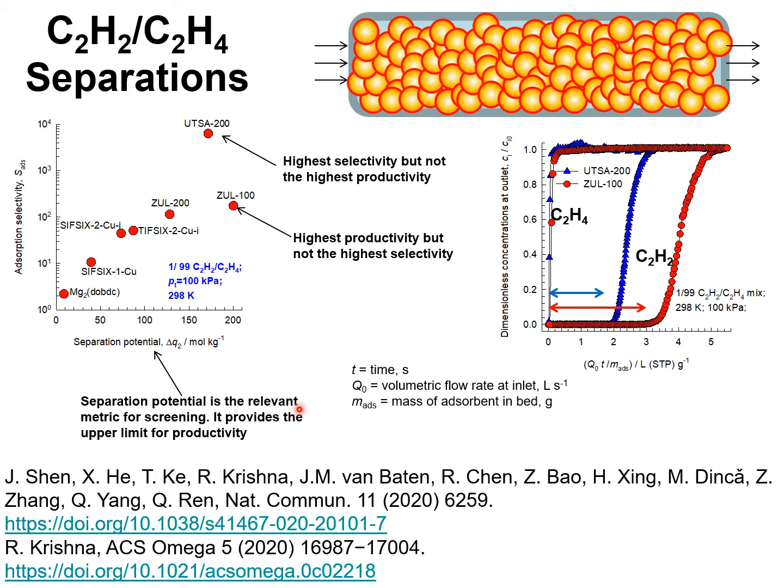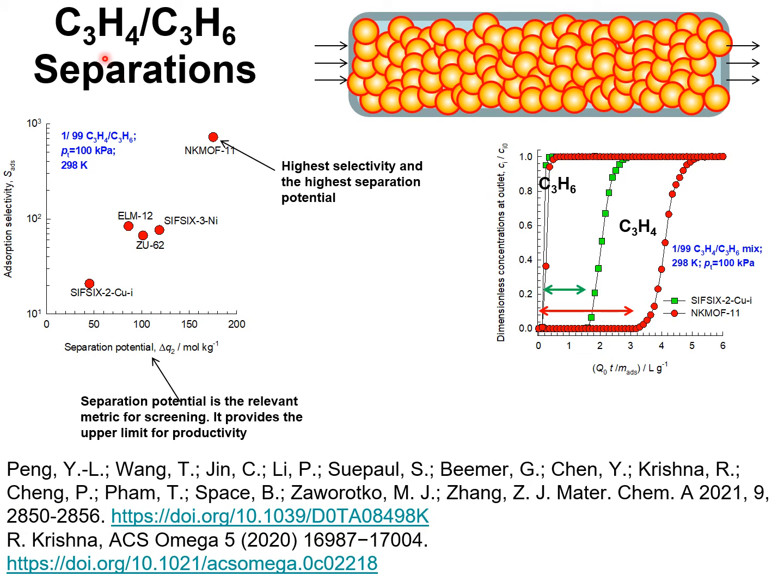In the transient breakthrough simulations, we take proper account of the intra-crystalline diffusion, as well as the fact that the concentration fronts in the actual adsorber will not traverse the column in the form of shock waves, but will have a more distended character that reflects the finite selectivity of adsorption with a given MOF.